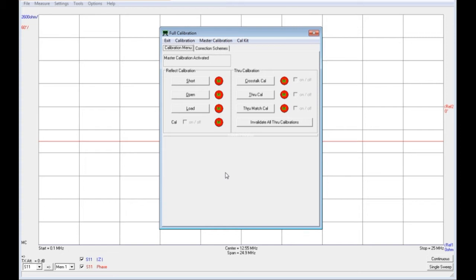Very simply, what I've got connected to the VNA is the SMA to BNC adapter that we looked at before, the high quality Hewlett-Packard BNC cable, and the BNC to dual banana plug inputs connected to the primary coil of the cylindrical coil on the bench. Now, what I'm first going to do is calibrate just to the end of the BNC cable. The plane of reference that I want for this calibration is the end of the BNC cable, and that would be my basic calibration for the set of results that I'm going to show here.